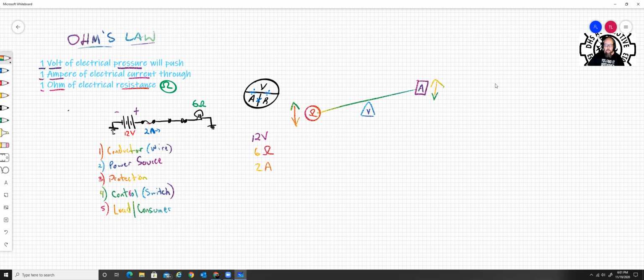Okay, so let's go over this one more time, because while it was instantaneous for you, there's been a few minutes for me. If my voltage remains the same and unchanging, and my resistance drops, my flow goes up, my amperage goes up. If my volts remain the same and my resistance goes up, my flow will go down.